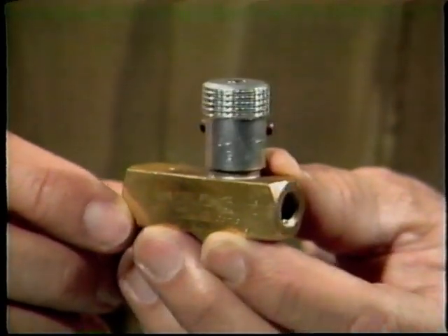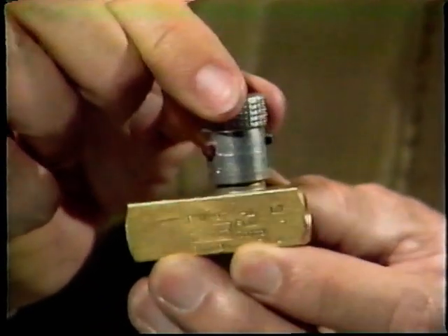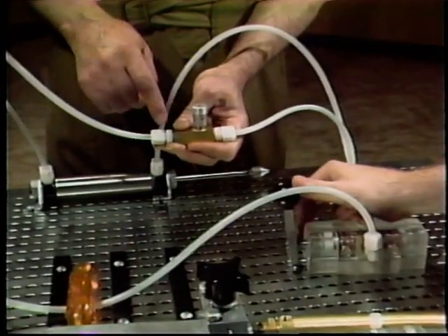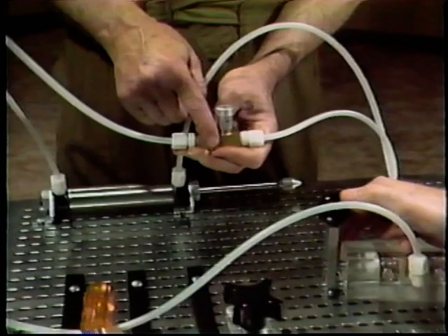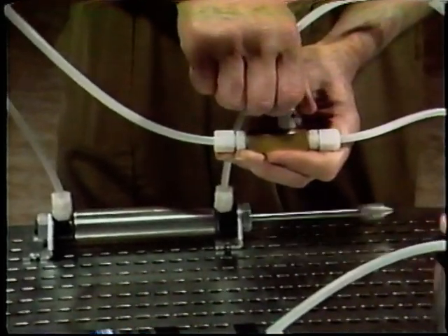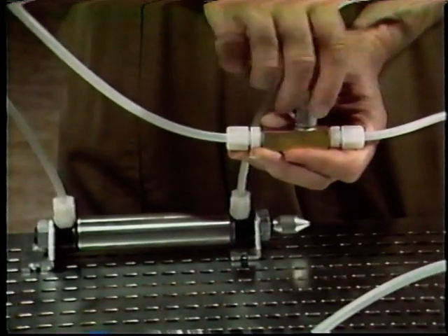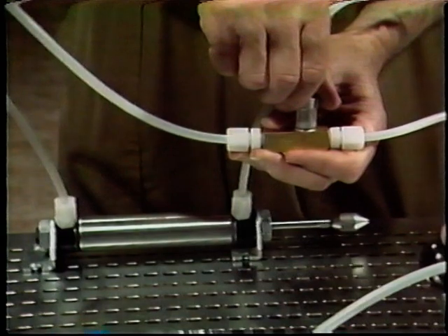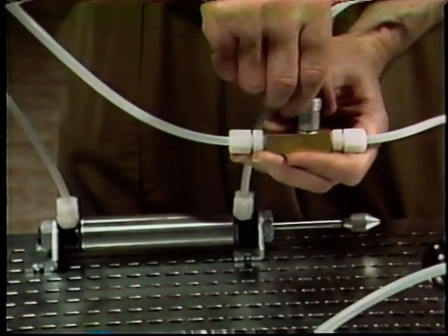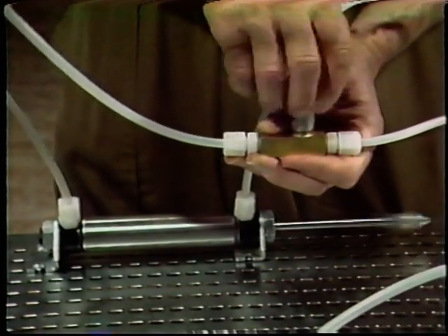This is a typical flow control valve. It is used in pneumatic circuits to affect actuator speed. Here it is in action. The flow control valve here is slowing the speed of this cylinder by acting as a restriction to partially block flow in the circuit. And as we explained in Lesson 7, the speed of actuation of the pneumatic cylinder is affected by how quickly it can be filled with air at its inlet and exhausted of air at its outlet.